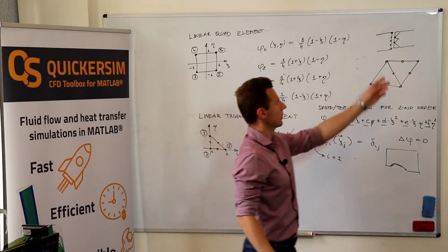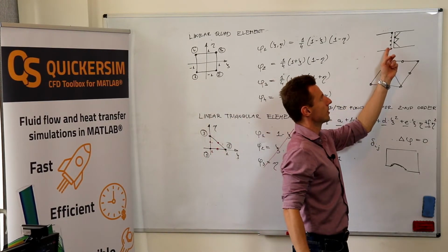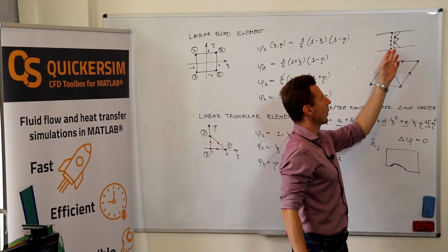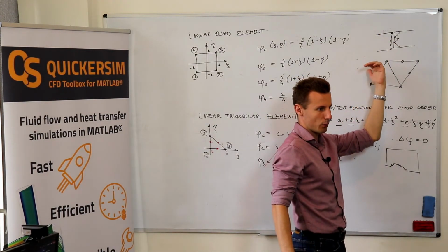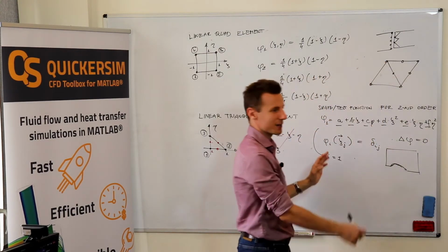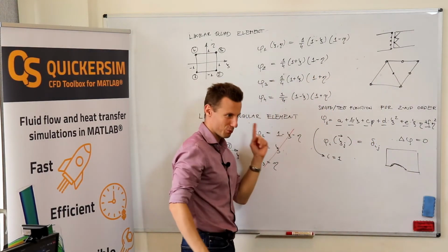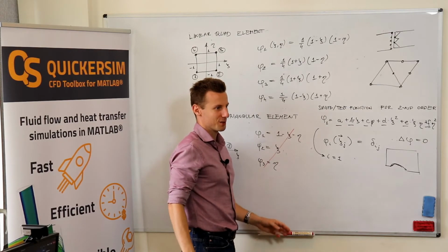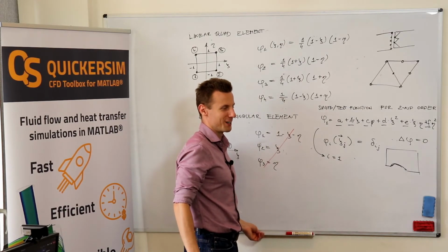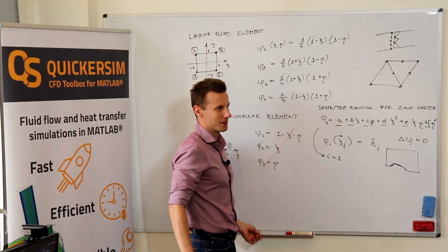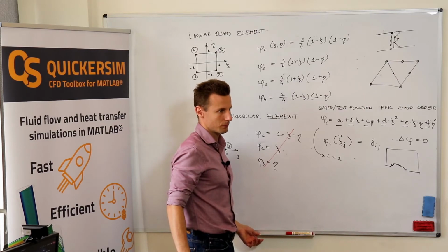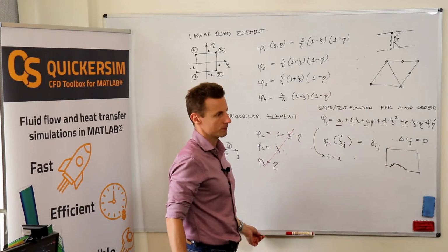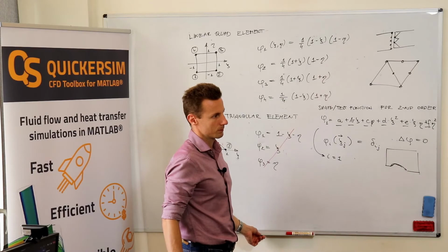You just need to derive a smart way of interpolating from one mesh to the other and the other way around, because you need to assemble the global matrix, and that one is tricky to do properly without errors. Yeah, we are doing it in contacts. You can do that. What about overlapping meshes?